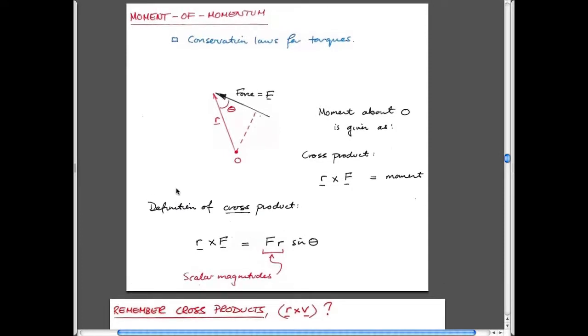When we dealt with mass flow rates, we talked about dot products and what those mean. It means that we get the component of velocity perpendicular to the surface that it's coming off. The idea of moments of momentum is also pretty straightforward. If you have a pivot point, and a force acting at a location with some lever arm, R, then to make it unique, we can't take this lever arm with an arbitrarily oriented force.